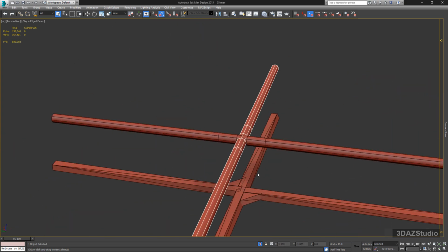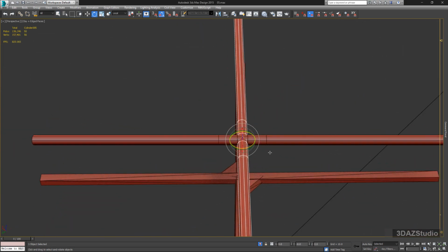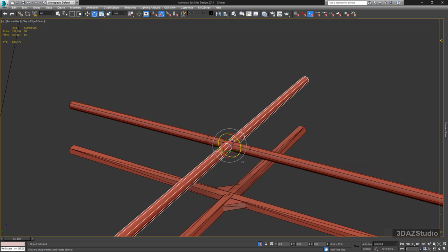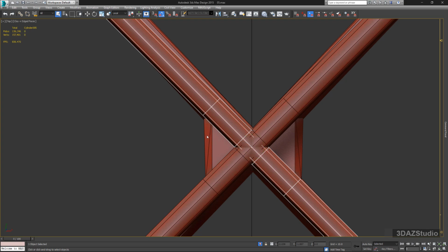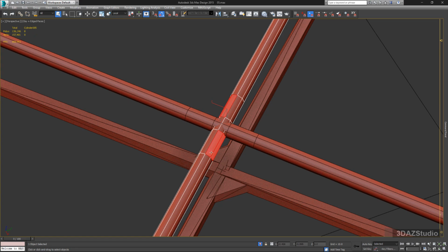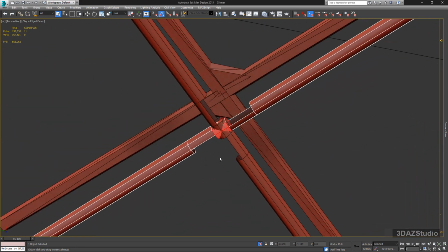To correct this, rotate one of the instances 180° around the local Z-axis. Editing multiple instances can be complex, so let's leverage the benefits of instances while we can. Now, let's clean up. Delete the polygons at the center of the cylinder and remove the cap polygons.